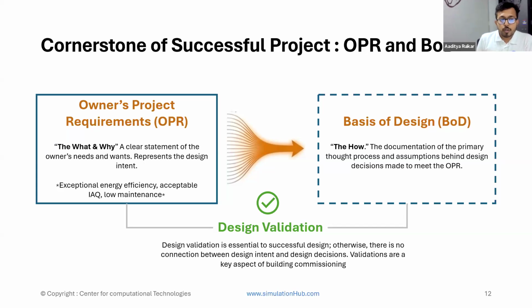The owner's project requirement is nothing but the what and why, or wants and needs, of your owner, like exceptional energy efficiency, acceptable IAQ, low maintenance, or the owner might want to achieve some rating system or apply for some tax incentives.